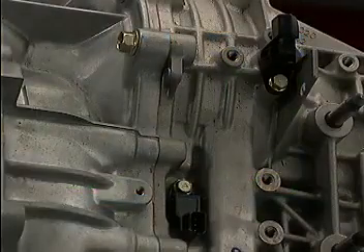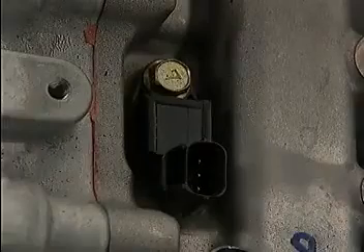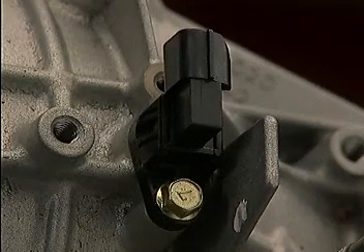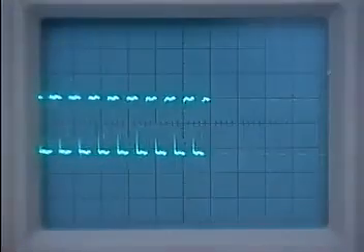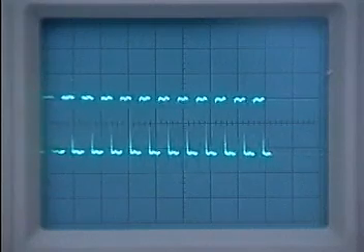Control information for the transaxle is sent by pulse generators A and B, now referred to as input and output speed sensors. They are designed so they cannot be accidentally interchanged. Instead of AC generators, they use Hall elements to generate outputs similar to a crankshaft position sensor.